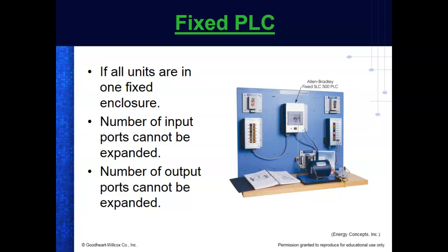So the advantage of a fixed PLC, it's a lot cheaper, but what? You can't add to it. What you buy is what you get, and these are still very popular, doing small applications, right? You understand that? Number of input and output ports cannot be expanded. The amount of memory in it can't be added to. The way the memory is organized can't be changed. So it's pretty interesting. But these things are still very popular.